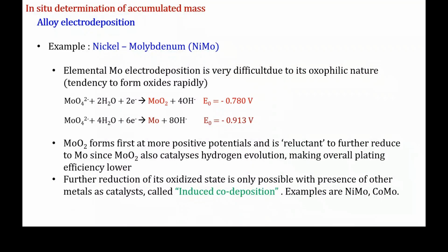So if you've seen how tricky it is to try and understand nickel electrodeposition, this part is becoming even more complicated, because you have two metals depositing, and you have different stages of deposition and electron transfer, and different intermediates catalyze different reactions, and all of this is competing with hydrogen. So there's a lot of competition between adsorbed species on the surface and all kinds of things, and it's all sensitive to the composition of the bulk solution as well.